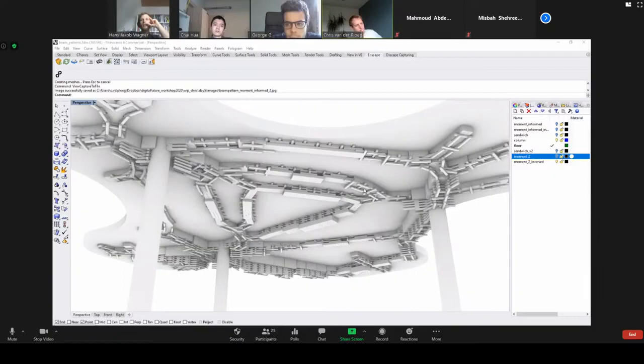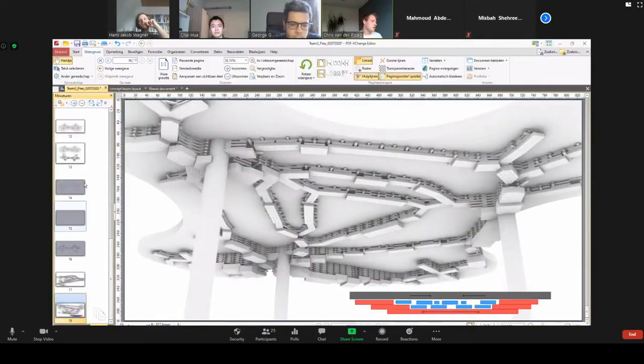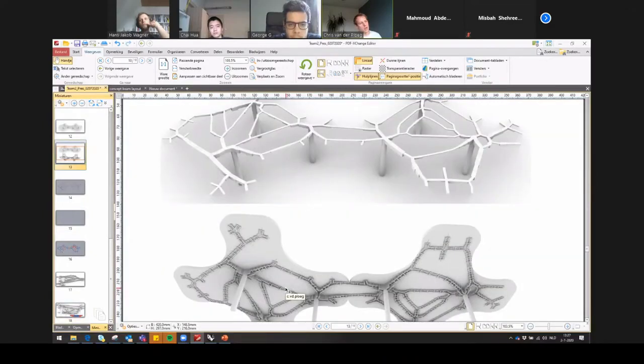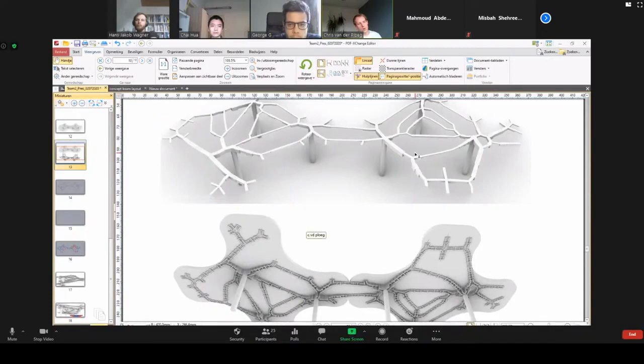So in terms of generation, what we did is that we generated 2 completely different structures, one with slats and one with normal beams, and then we started to swap them out. For some aspects and some layers, we took parts of this structure, and for the other aspects, we took parts of that structure. Each individual structure is completely collision free. Whenever you start to mix and match them, there are some issues to be solved, but basically it means that you have to cut the elements a few times.